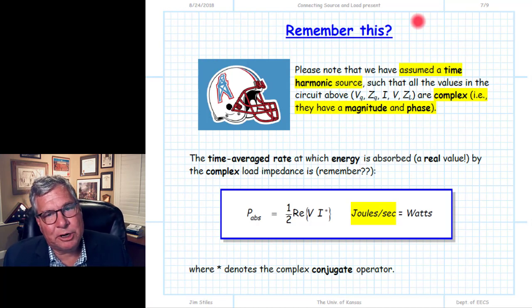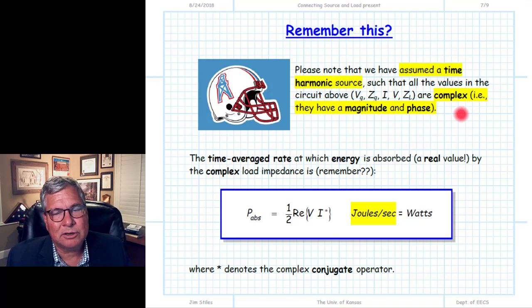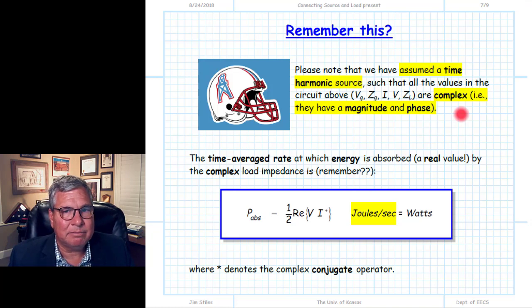Harken back then to your freshman year when you had such a simple circuit, a voltage source with two lumped impedances in series, and we want to find the voltage across the second impedance and the current through both impedances there. We can use voltage division and Ohm's law and define both the voltage and current. Once we find that voltage and current, again, these are complex values, we can determine the most important thing to us with respect to radio engineering, the rate at which energy is flowing across that interface, the rate at which energy is flowing from the source to the load. And of course, rate of energy we call power.